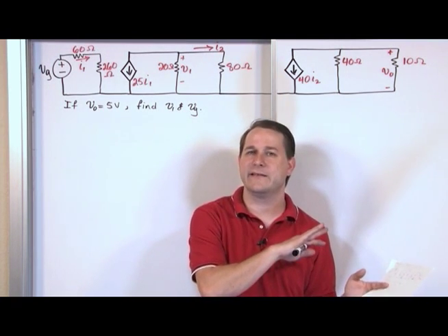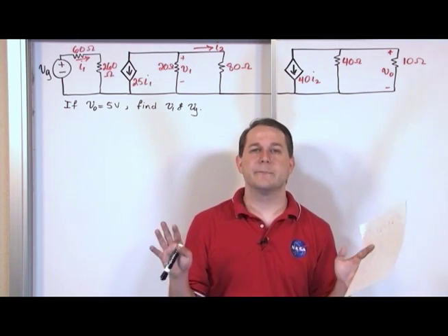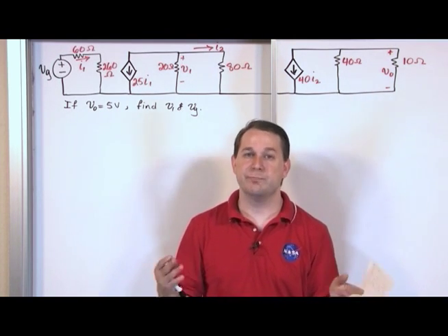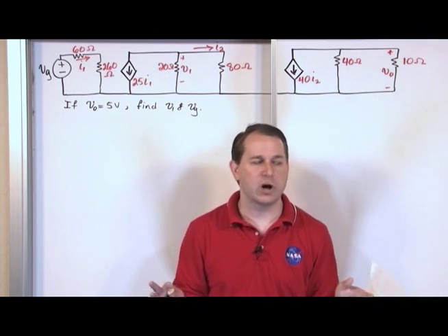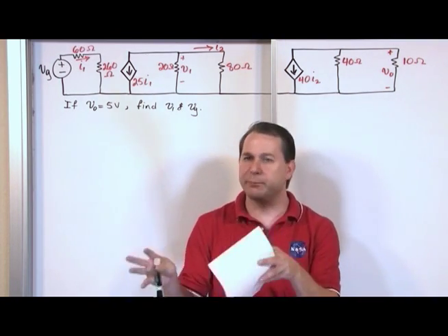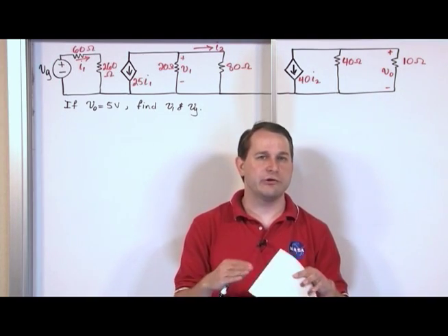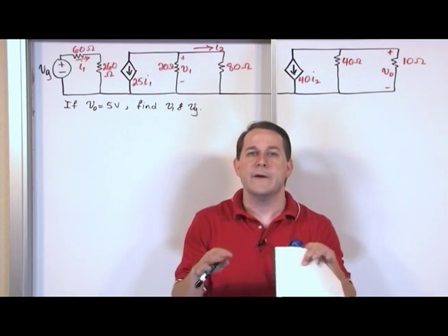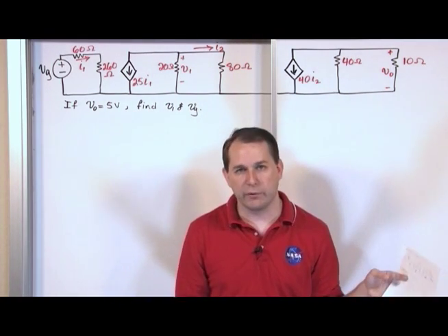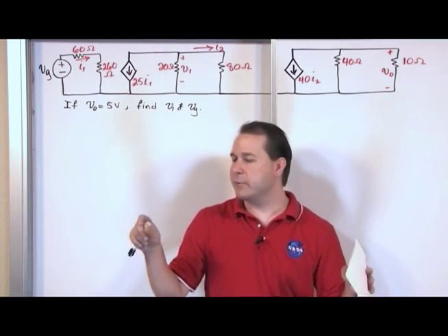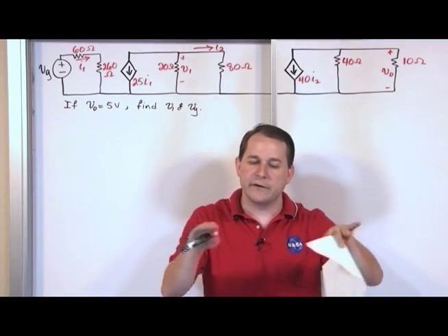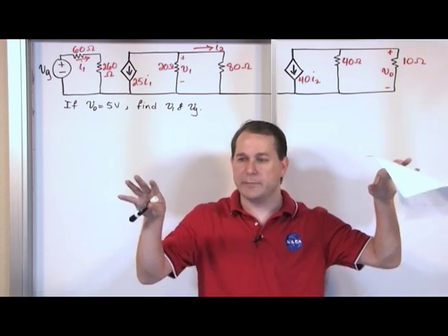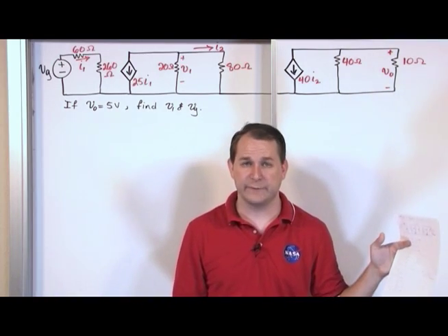We're going to get into this idea a lot more. But the bottom line, the thing to pull away from it, is the best practice when you build circuits that are commingled, co-located, part of the same system, but they're separate circuits, right? You really need to make sure that the base voltage, the low voltage of their sources really, are all at the same potential, all 0 volts. So that when you have a battery here and a battery there and a source here and a source there, all of their 0 potentials are in the same place, so that they're all playing nicely and nobody's floating up and nobody's floating down, creating these dangerous potential differences between each other.